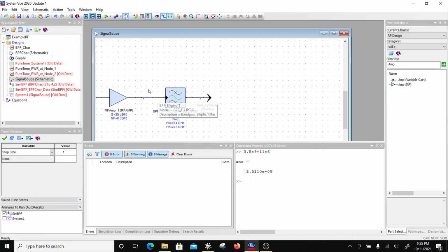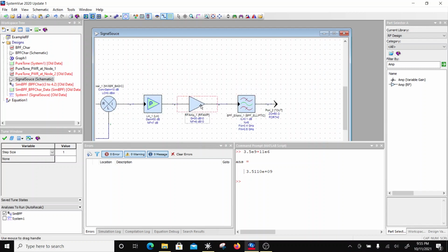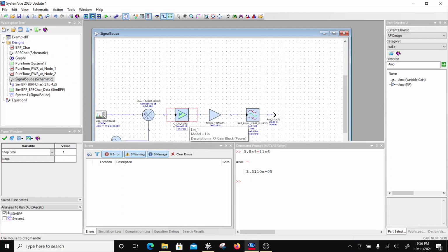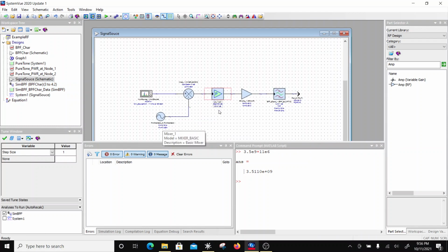So basically this is an input stage. So over here you will have an antenna, and this is the image reject filter, and this is the PA, and this is the driver for that PA. So here the LNA will basically be over here. The input of the LNA will be from node 6 here, right? So this image reject filter is shared along with the antenna between transmit and receive path. So I hope you understood that. So this is a typical transmit chain, the simplified form of a transmit chain, right?